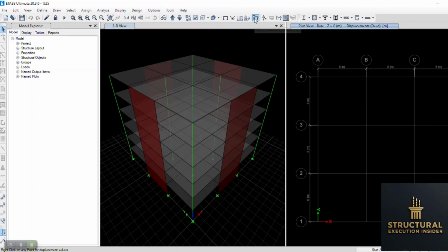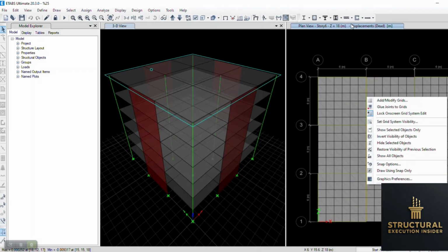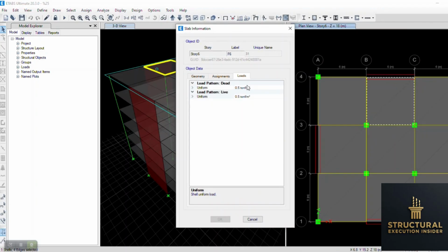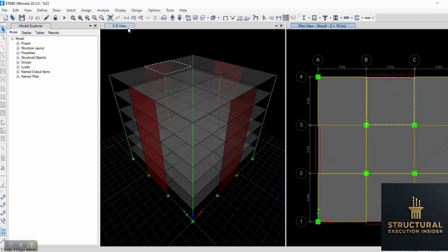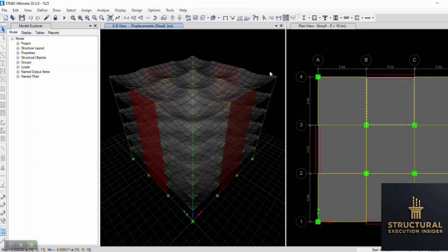Now the behavior becomes very interesting. During dead load and live load, the shear walls still exist. So gravity stiffness, gravity force transfer, and diaphragm interaction all remain completely realistic. However, during the earthquake loading stage, the walls no longer participate in lateral resistance. So the seismic forces are redistributed primarily into the moment frames.